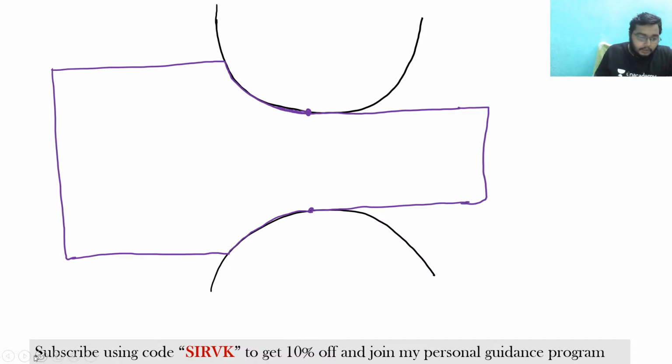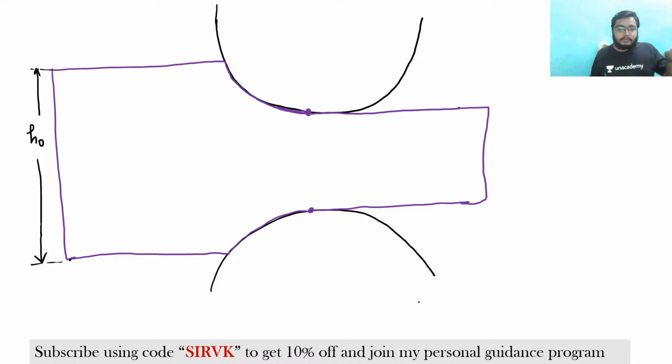Let us assume this length to be h naught. H naught is the thickness before the rolling operation. This is the final thickness after the rolling operation, hf.